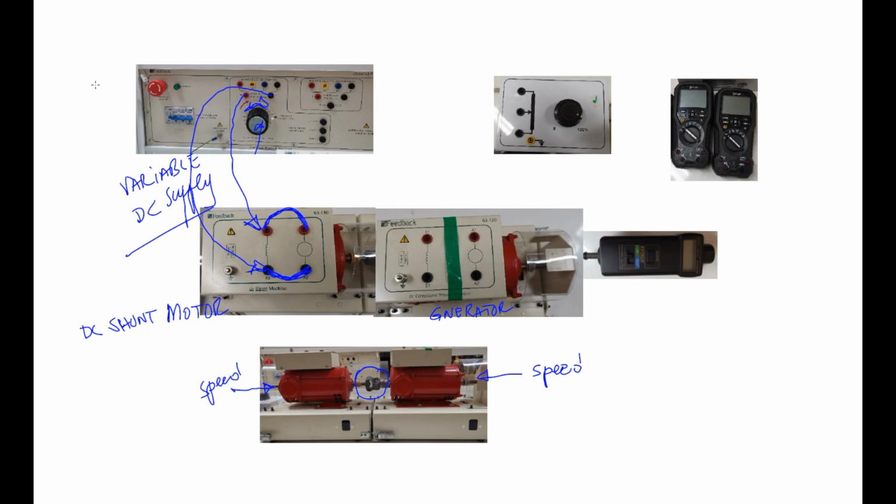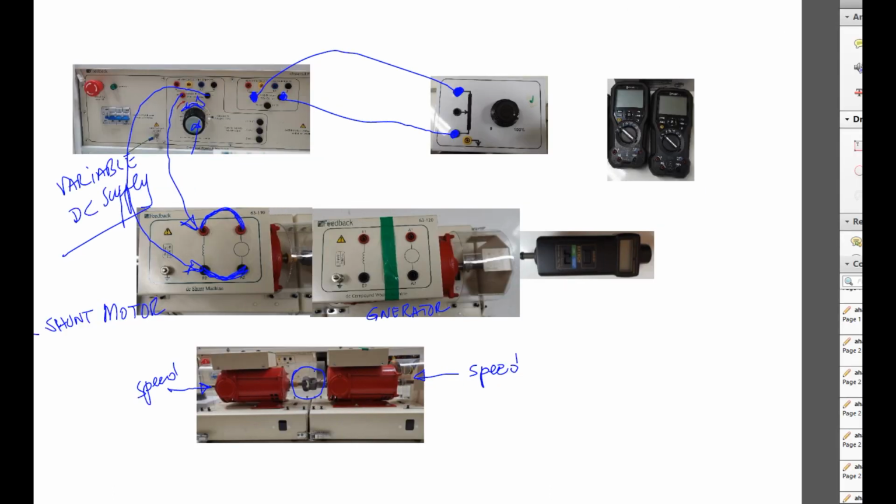Now, let's make the other DC, the fixed DC, variable. We'll take the plus of that fixed DC supply and connect it to the upper connector of this rheostat, and the minus to the minus here, not the ground. These two are not connected. If you connect your minus to the yellow one, your supply will be floating, with no coming back path for the current. So this will be supplying our input for the rheostat, and the output.